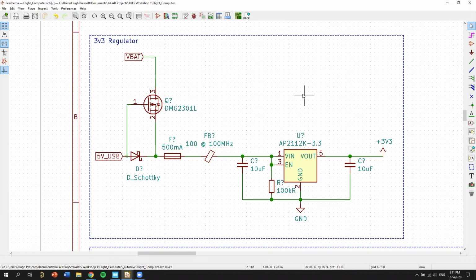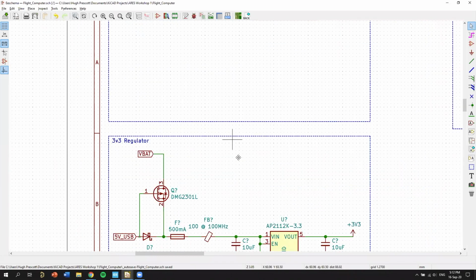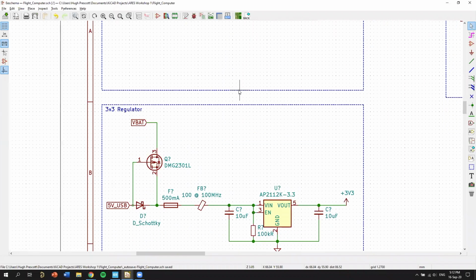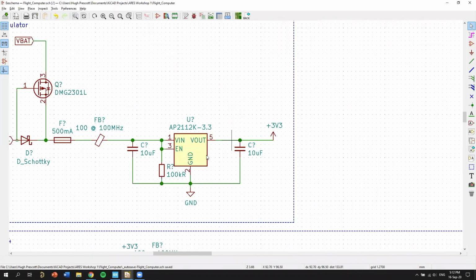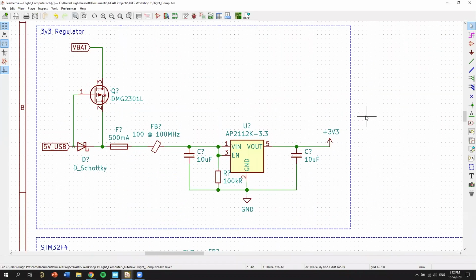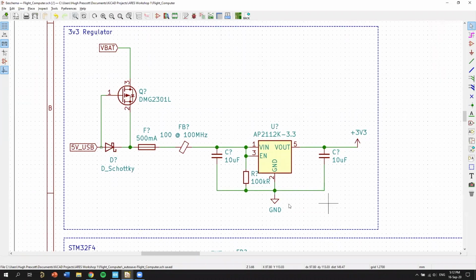Actually, I don't know how a buck converter works, but a boost converter, you're pushing in all of this current into a capacitor and it raises the voltage above what your input is. So that's how we step up from, for example, 3.7 volts up to 5 volts. You can use a boost converter. Or here, in this case, we want to use a buck converter, which steps it down to 3.3 volts. And you can get efficiencies of like 96%, which means you're not really wasting any heat.